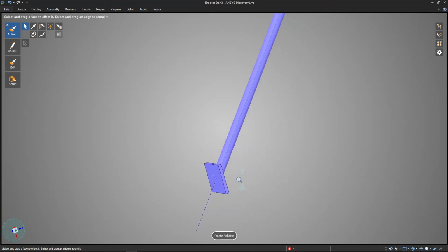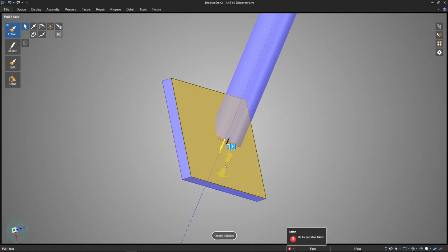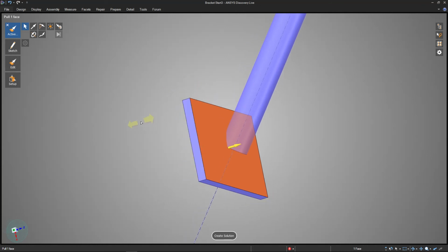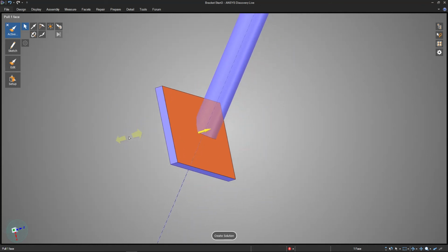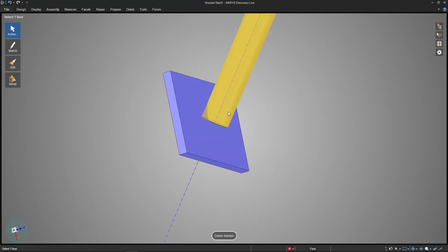So you might try some of the same techniques that we did with using the pull tool before, see if that resolves our issue. Trying to select this face and pulling it up to the back. Doesn't seem to like that. Pulling it up to the front. Still run into some issues here. So how we get around this kind of situation, if we can't just do it easily like we did before, we should combine these into one object.